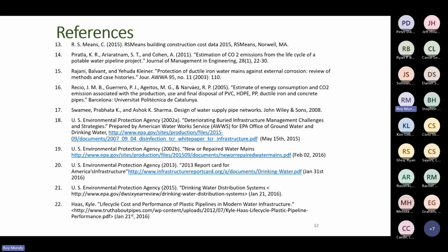But specifically, 2 years ago, maybe 3 years ago, the Ductile Iron Pipe Research Association went to the very first cement-lined cast iron pipe that was installed in this country in Charleston, South Carolina, which was in 1922, 100 years ago plus, and effectively ran a flow test on that pipe. And that pipe C factor came out to be 138.